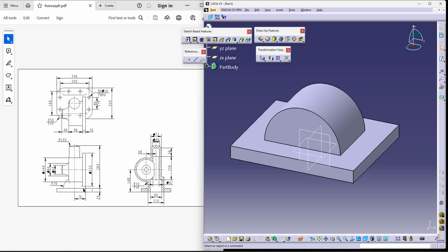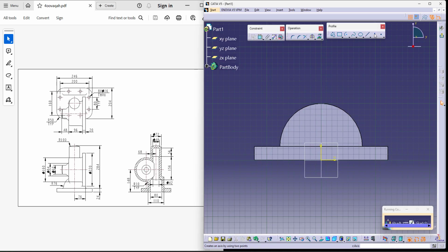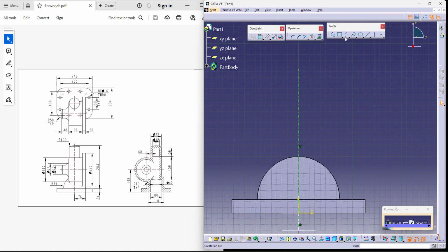On top of it you do have another one which is a cylindrical feature of 28 arc, 100 with 72 diameter. Let's try to make that. While making it, I'd prefer to use a shaft because I need to maintain all the dimensions. I'm using the shaft command and I'm using my axis as the center, of course. Now the arc on the top is actually 100.